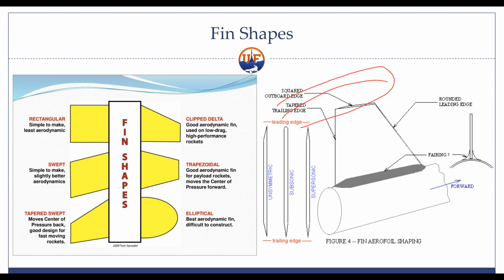But for a rocket, it's not the best, because what's better for going fast is actually sweep. Sweep is when you take this rocket fin and you sweep it down like that. You're going to learn about this in compressible flow, but essentially, if the wind's going this way, it's actually going slower against the fin.